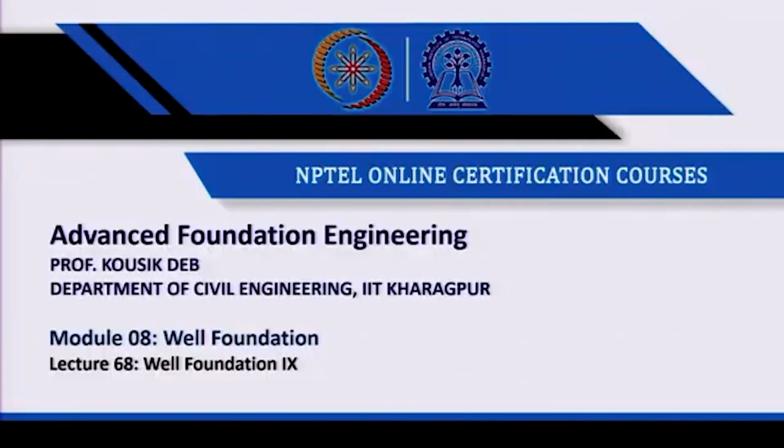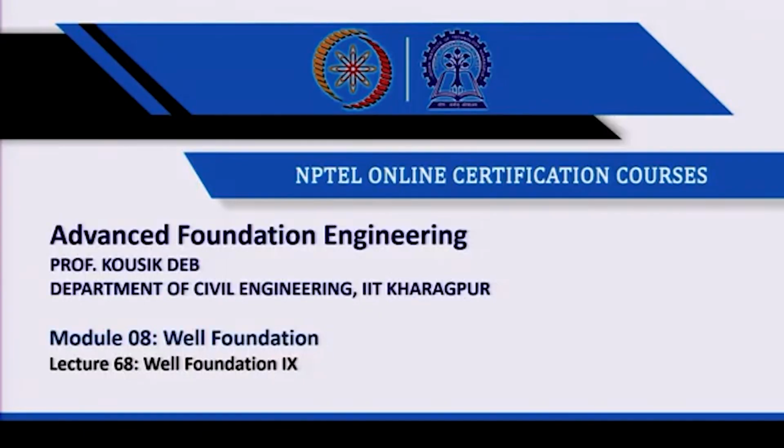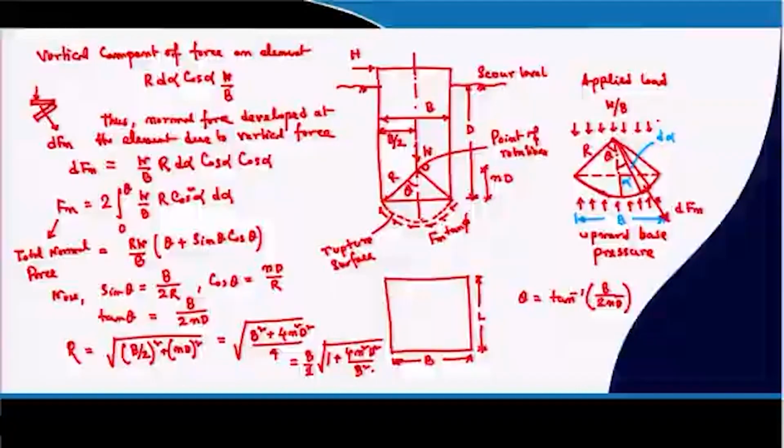So, last class I discussed how we can determine the moment due to the friction force acting along the side of the well, and then I discussed the rectangular well. Now, today I will discuss the circular well first.